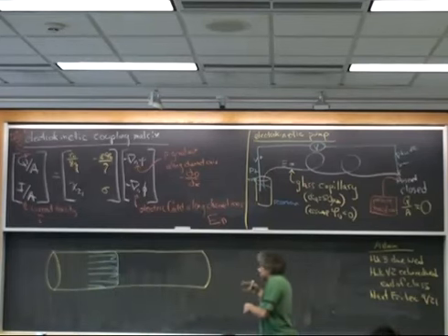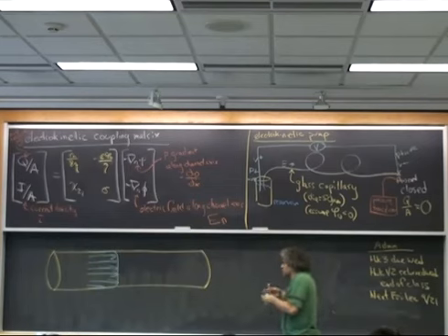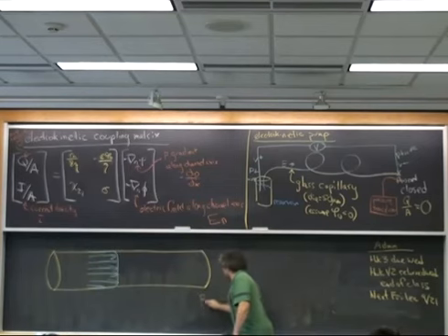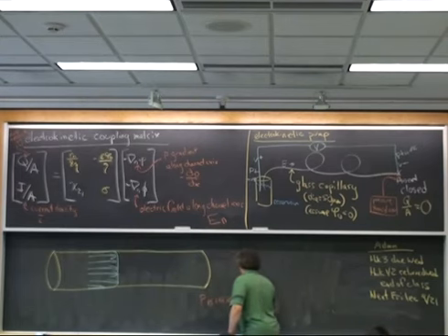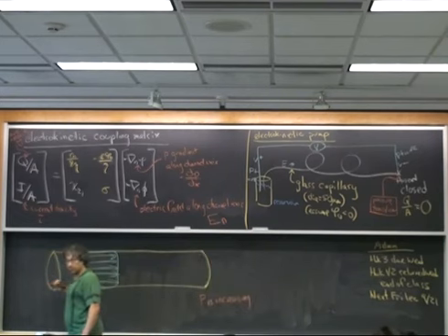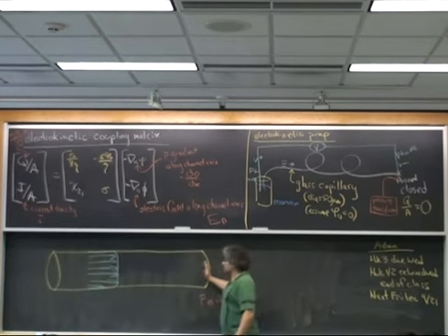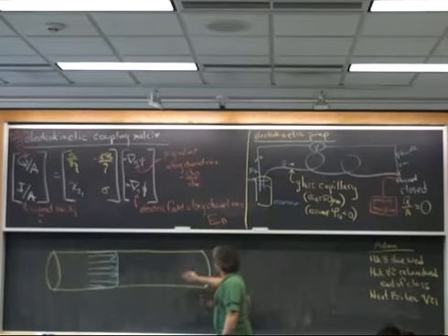So as this is flowing, the compliance of the system is taking some of this extra volume, filling the system up. The net effect is that the pressure at this end is increasing. I'm increasing the pressure at the downstream end. I'm not increasing the pressure at the upstream end. That's connected to the environment, right? So this pressure starts to increase. As this pressure starts to increase, now there's an additional component on this system. Now I have a pressure-driven flow.